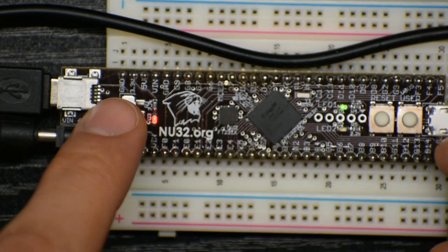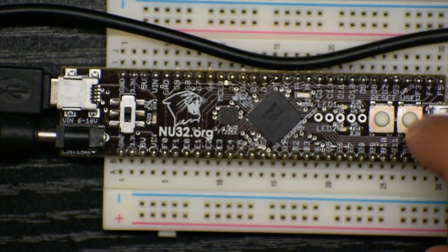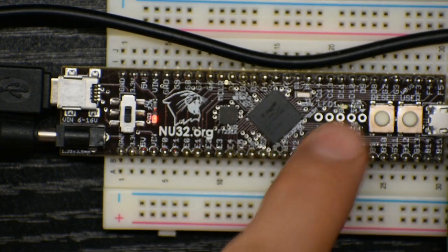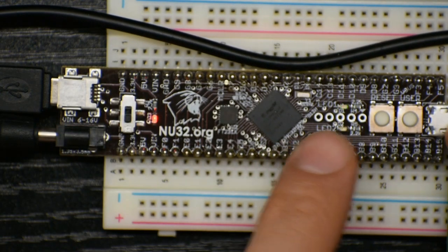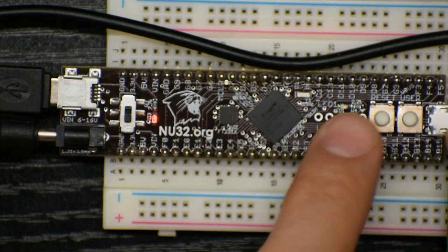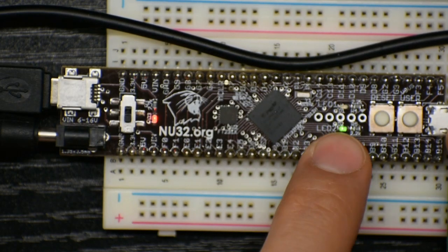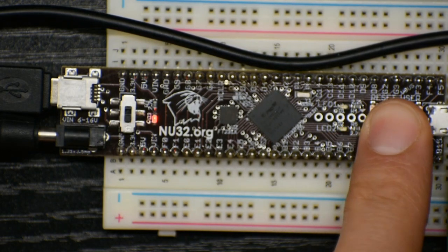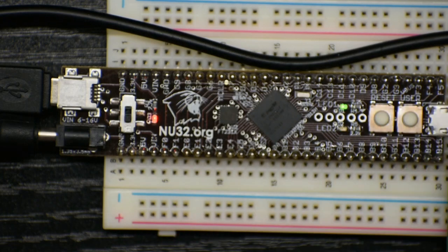So another way I could do that is I could turn off the board. I could hold the user button while I turn on the board, and it will go into bootloader mode. If I'm ever in bootloader mode and I don't want to be in bootloader mode, I could hit the reset button, and my program just starts to work. And eventually you'll get so used to this that it's a rolling action. Push and hold reset while you roll over to user and then let go of reset.